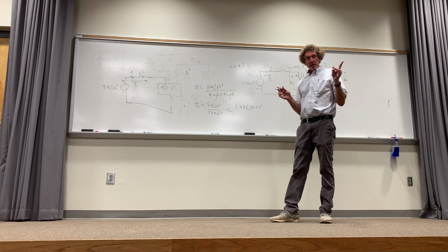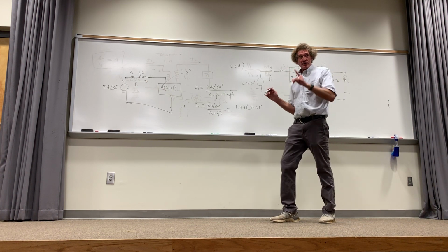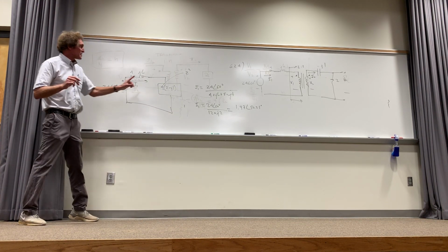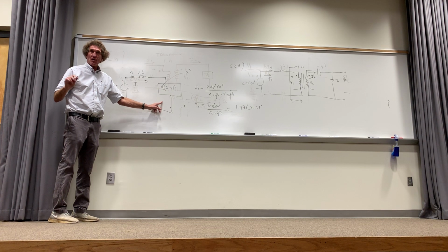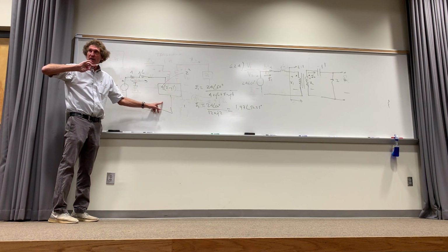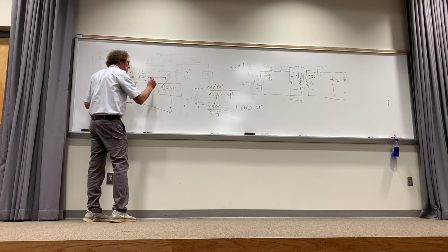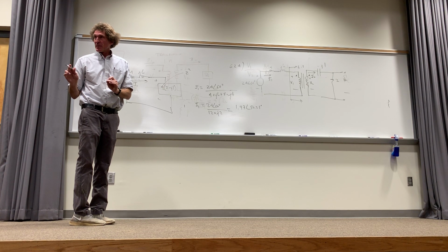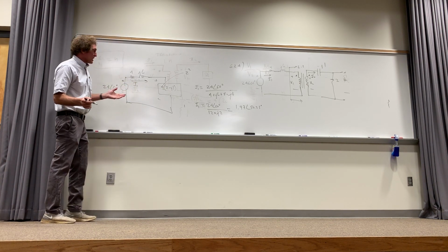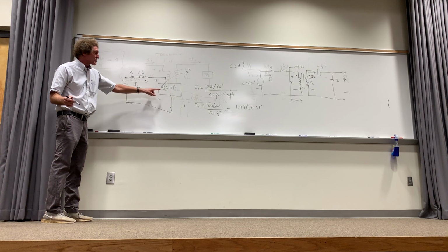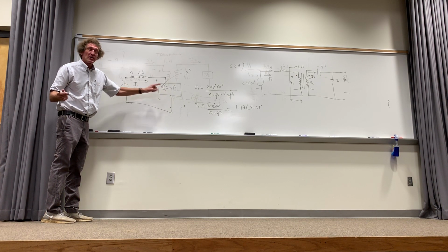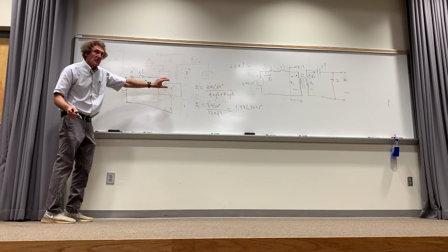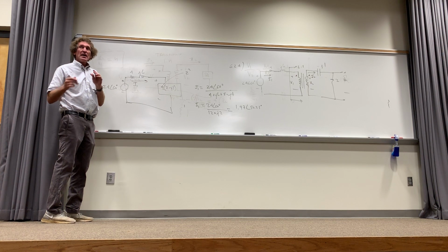Got it? Now, in doing this, listen carefully, because this is a question I didn't address well. You see that this is the reflected impedance of the transformer. Y'all follow me? It's the secondary reflected to the primary side. This voltage right here is my V1. So how do I get V1? Well, pretty simple. I got the current I1. If I just multiply it by that, I got V1. I could have done voltage division too. I could have taken this times that impedance over that impedance plus that impedance. Either one will get me there.